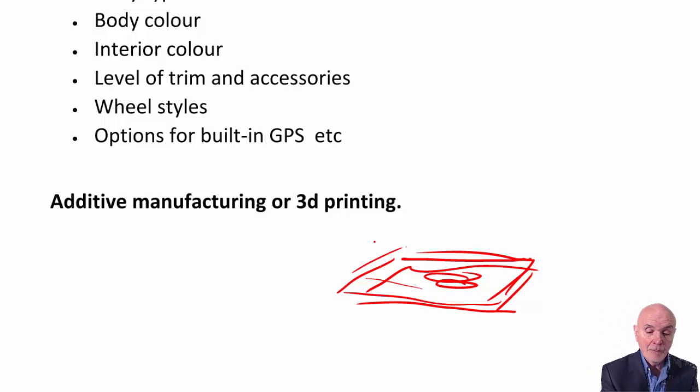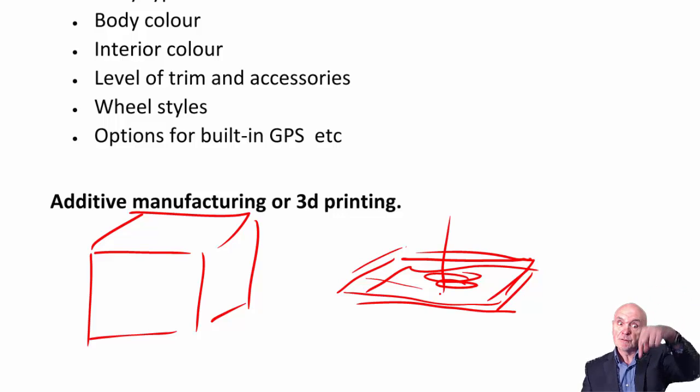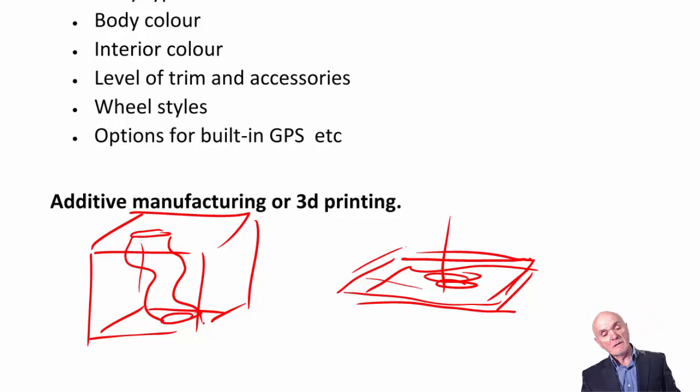And what you're going to end up with after many of these layers is really a kind of cube shape here. But maybe instead of the holes all being lined up, which you could do by just drilling a hole, what we actually managed to do, because we shift the position of the hole very slightly on each layer we build up, is produce a really quite complex shape going through it that would be very difficult to produce using conventional manufacturing.